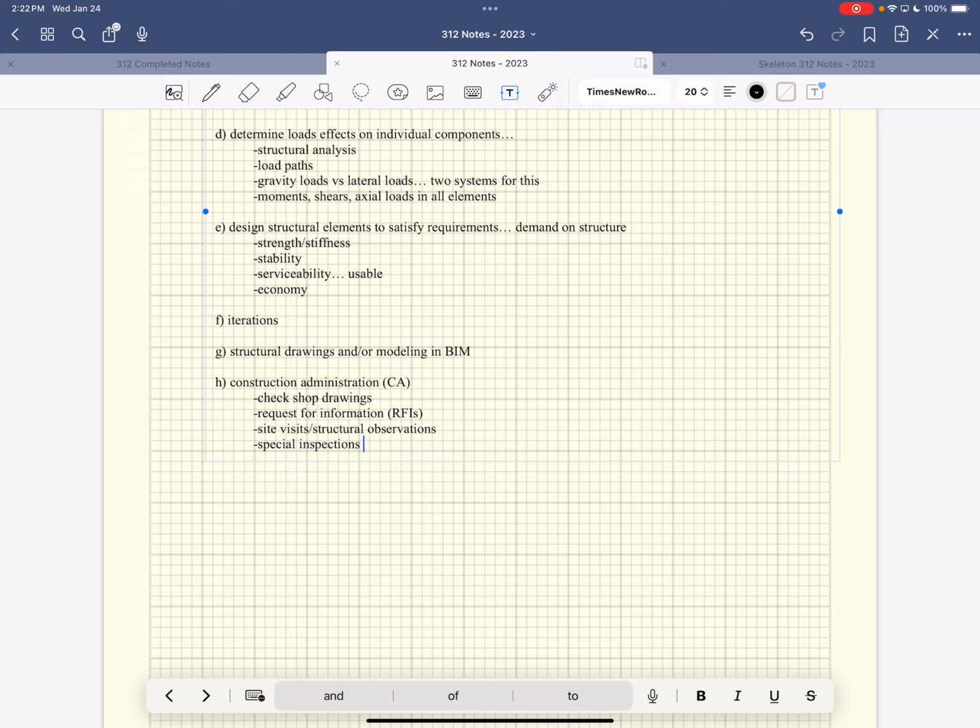And the code isn't just going to take your word for it. So they have this thing called special inspection. And actually, it comes from outside the structural engineer. If you design the building, you don't do this. It has to be a third party. They come in and double check that you're doing what you said you're doing, because you got rewarded already. So we'll get into that. That's special inspections. Somebody else, a third party, comes in and says, yes, they did what they said they were going to do. And then they were justified in getting their reward and using less loads.